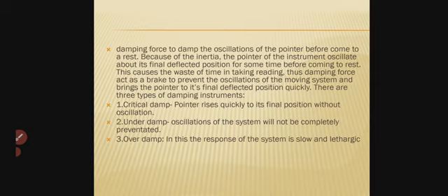The damping torque acts only when the pointer is in motion and always opposes the motion. The position of the pointer when stationary is therefore not affected by damping torque. The degree of damping decides the behavior of the moving system.